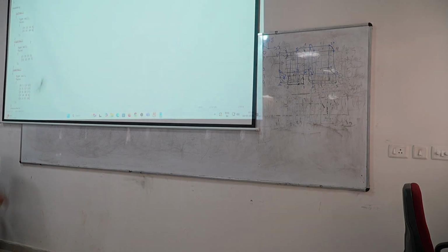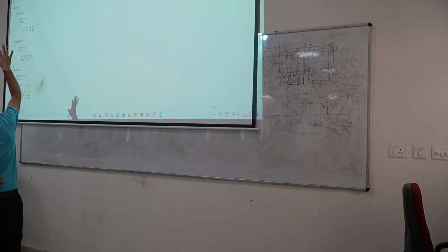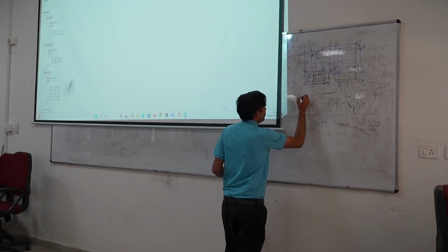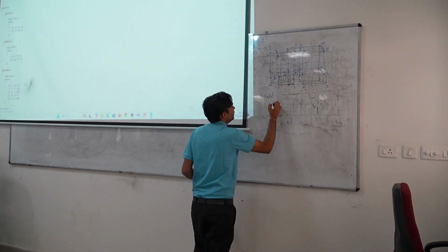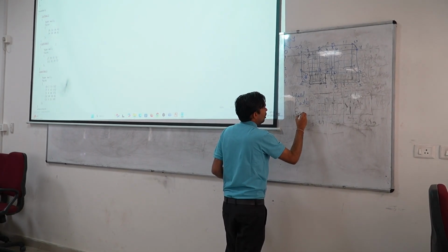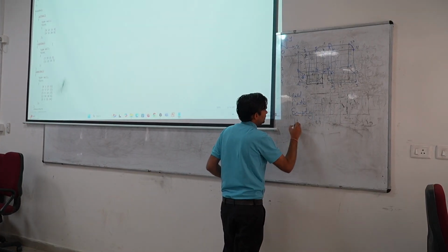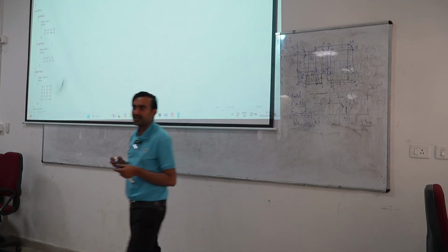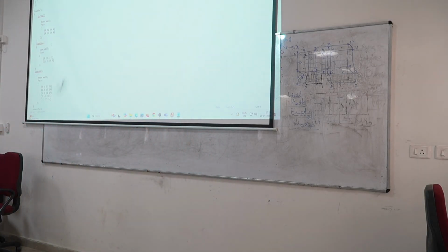After that, right wall. After defining the vertices, you need to know the type of this boundary. Typically the type of boundary is specified either as wall or patch or empty or wedge. So, typically 4 different types are specified.